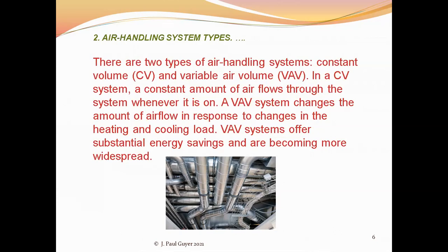It remains constant, so your thermostat isn't telling the air handler, so to speak, the chiller, to deliver air at a colder temperature. It's just delivered at a constant temperature. So VAV systems are the state of the art, if you will, and the most energy efficient.